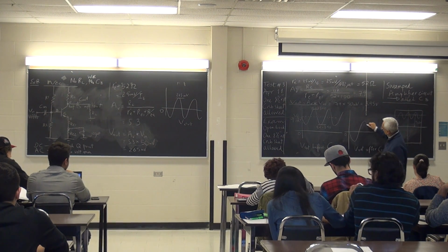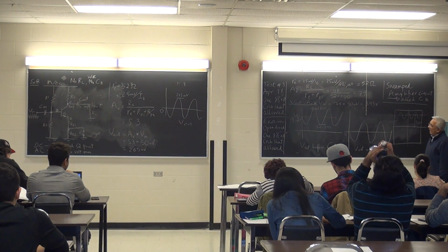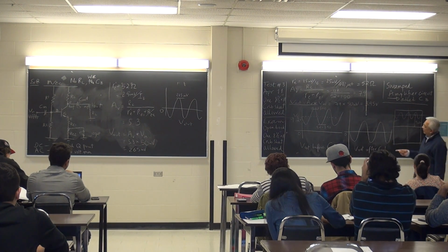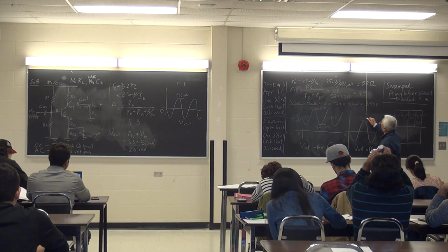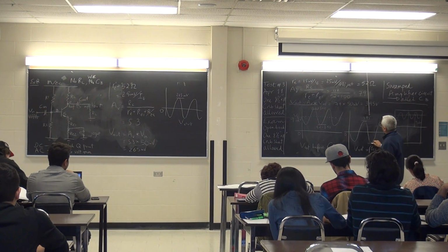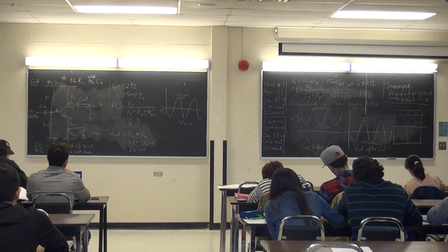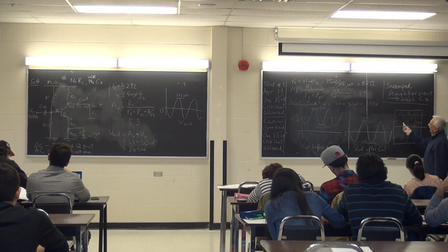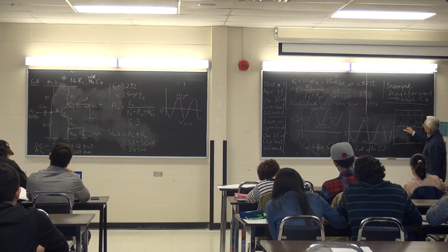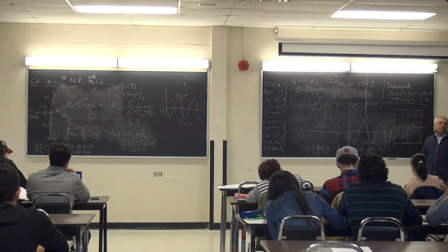Instead, this is what I will see at VL, after CL. Okay? 0, no 9.2 volts here, just 3.95, and minus 3.95. Okay? And on a scope, what would I see after C out? I would see that graph here, not shifted up. That's what that means.